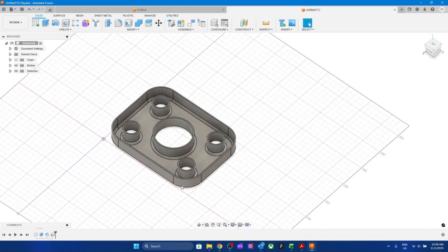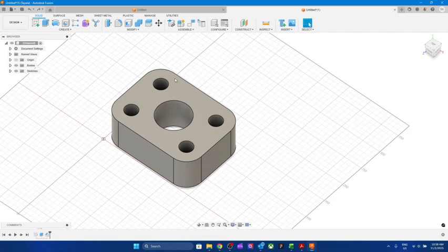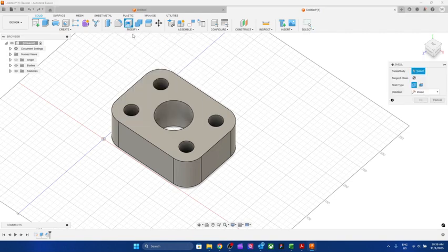Right? Okay, I think, Doctor, can you explain shell? I can't find it. Okay, this is where I was. Can you see the modify tool up and this shell next to fillet? Yes, okay. Next to fillet, click it.